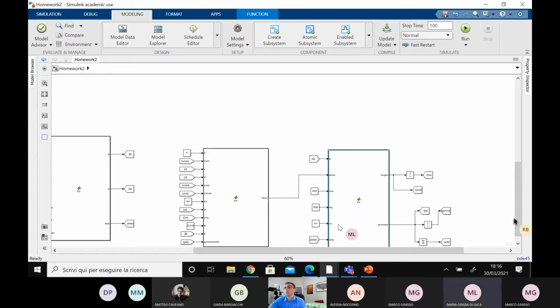Okay, so it is one way to avoid the algebraic loops, because it just means that it doesn't know what to do at the first time step. But you mean any time that I have, for example, an omega double dot coming in here, I should put a memory block? No. Here. Right after you generate the omega dot, put a memory here and put another memory.